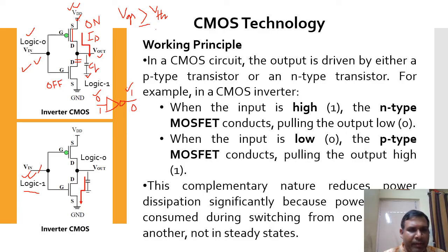So finally what will happen? There will be no positive charge carrier accumulation in this region. So this device will act as an off-state device, because there is no inversion layer. That means the circuit is totally detached from the main circuit. Off means there is no connection with the main circuit.